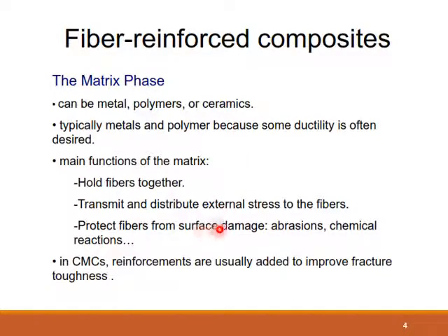Usually in a ceramic matrix composite, the fiber is there to improve fracture toughness, and I'll explain what this is. Fracture toughness is a unique property of materials that allows them to resist crack propagation. So you will now understand that in ceramic material, the ability to resist crack propagation is very, very low. The answer is simple. They are high strength, but they are brittle. So once a crack sets in a ceramic material, the crack just propagates easily. By that, it means the fracture toughness is very, very low. So one of the reasons for fiber reinforcement in ceramic material is to toughen it. By so doing, you want to improve the fracture toughness, that is, its ability to resist crack propagation. Once you do this fiber reinforcement in ceramic material, this is what you intend to achieve, so that the second phase you are incorporating into the ceramic material will serve as a hindrance to the propagation of the crack.